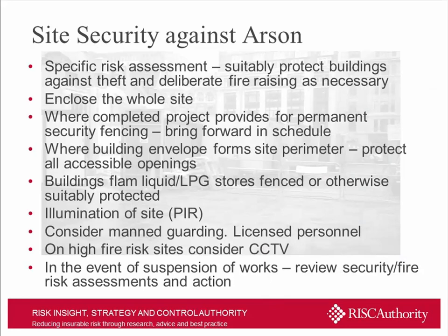Site security against arson, we mentioned that. I mentioned this a couple of times now. There are a number of things you can do to protect a site. Statistically, I think it's noted that enclosing the whole site with a decent hoarding is the best way of protecting the site. It's the most effective means anyway.